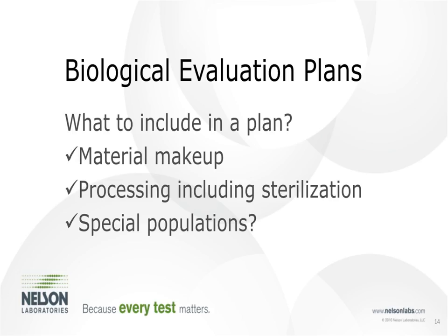So instead of saying, oh, it's medical grade, we're good to go, really delve in to see what constitutes those claims. A USP Class 6 is a great claim, but it does not include cytotoxicity. And it's very limited to, it's supposed to be for raw material plastics for container closures, but we see lots of medical device manufacturers or raw material manufacturers try to use it, but be careful, it does not include cytotoxicity. So all these things have to be evaluated on your materials, previous use, what changes may happen during the process, what impact does sterilization have on it.